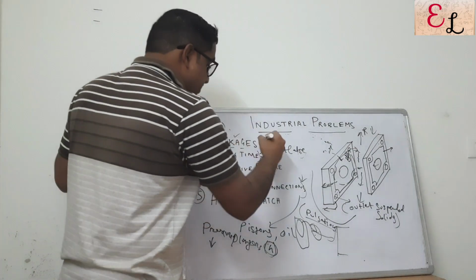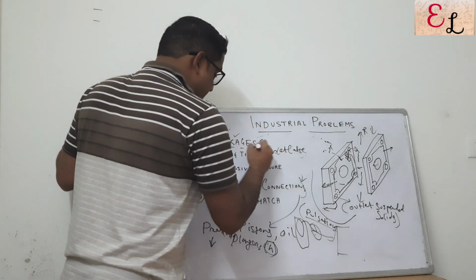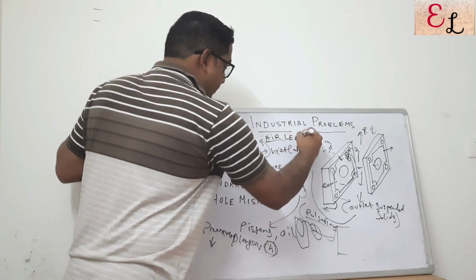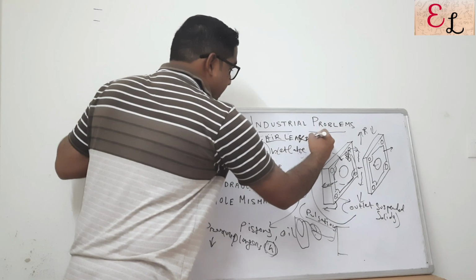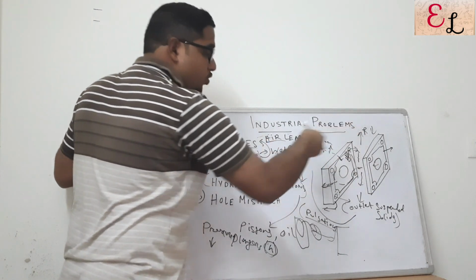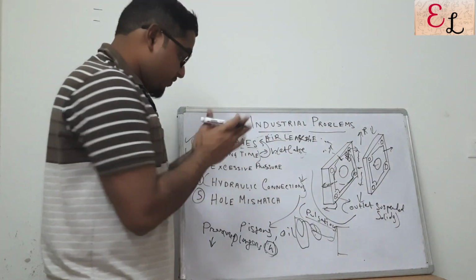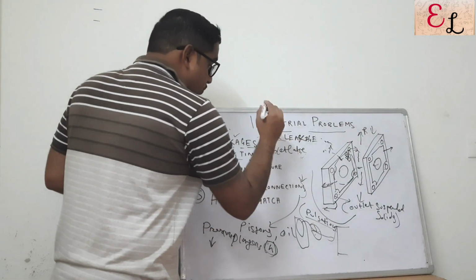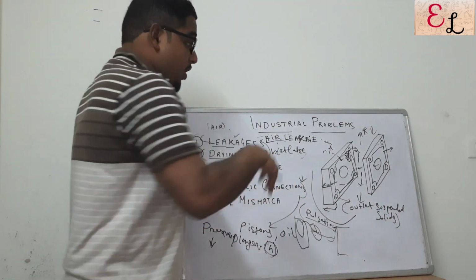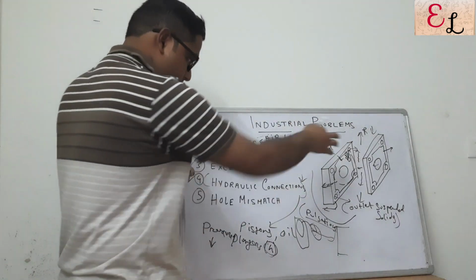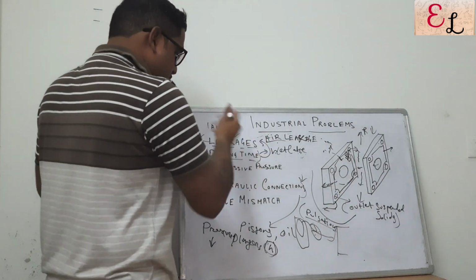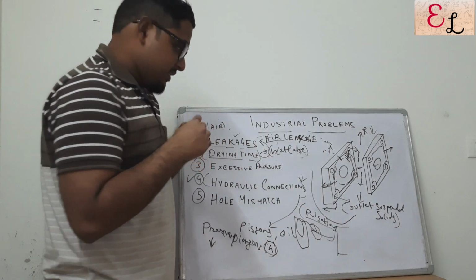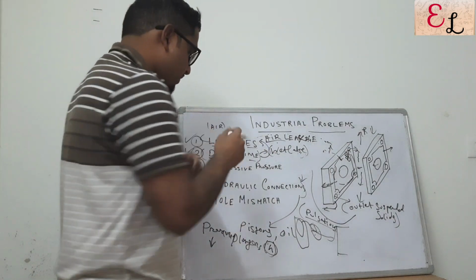So the primary problem is leakages. Air leakage. Whenever we pass air through the system, it leaks out either through the cloth, through the drain point, or through the top because of this hydraulic connection. So all are interlinked. So the drying problem is associated with air leakages through the system or from the system to the atmosphere, due to several reasons why leakages occur. And wet cake is the indication of that problem.